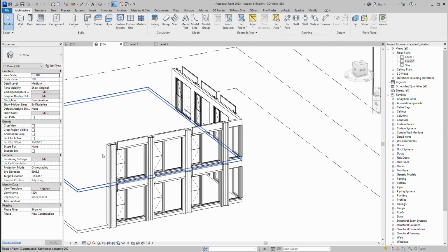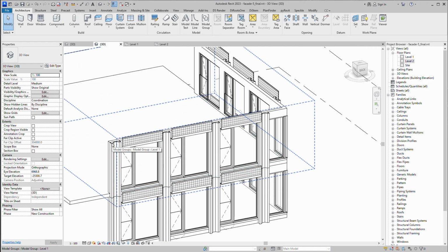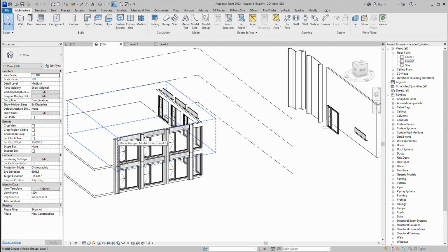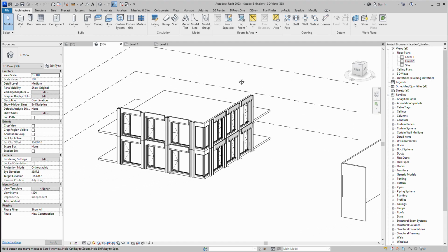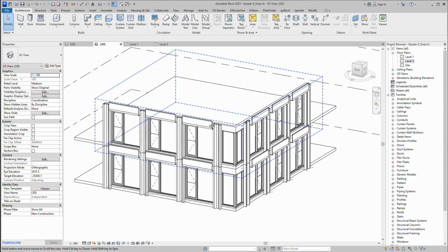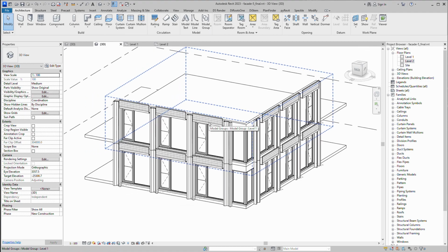And don't forget, because this is a system Revit family, it's working perfectly. I mean, with the calculation of the materials or something like that, so you can easily calculate the area. So I think with this tutorial, not everything you should create by families, but you can even use the Revit internal system families to create, let's say, internal families by the groups. Just be careful when you're working with the groups. Groups, on one side, are your friend, on the other side, your enemy. Be careful. So this tutorial is finished.